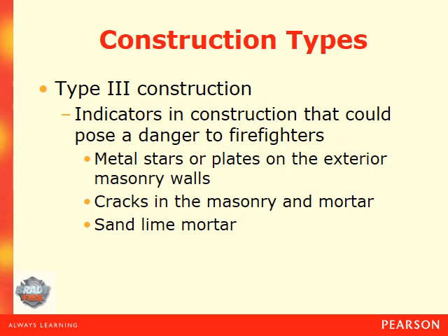So some of the problems with your Type 3 construction. Metal stars or plates on the exterior, and those stars and plates are designed to help reinforce the walls. So obviously the structure has been battered by time and has some structural issues that could fail during a fire.